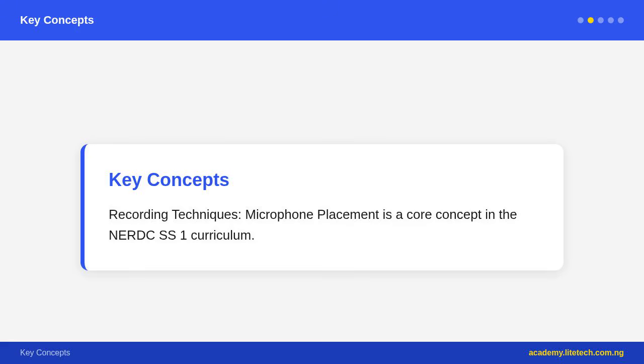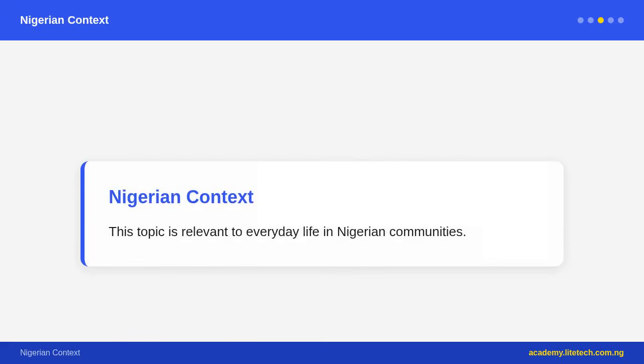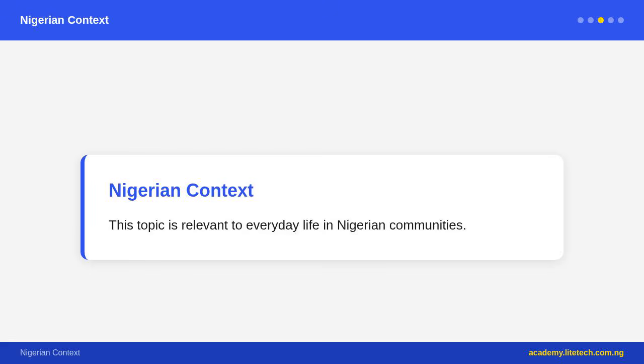Omnidirectional, sensitive equally to sound from all directions. Used when you want to capture the full ambience of a space. Bidirectional or figure of 8, sensitive to sound from front and rear, but rejects sound from the sides. Used in certain stereo recording techniques and for interviewing in broadcasting. Hypercardioid, more directional than cardioid, tighter front pickup, some rear pickup. Used where maximum isolation from surrounding sound is needed.